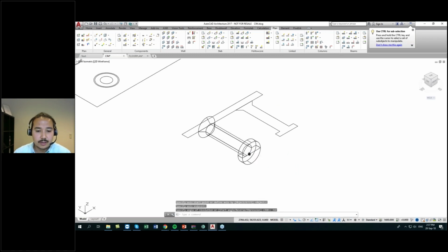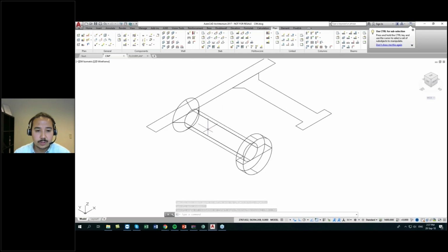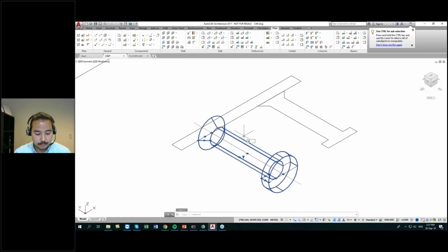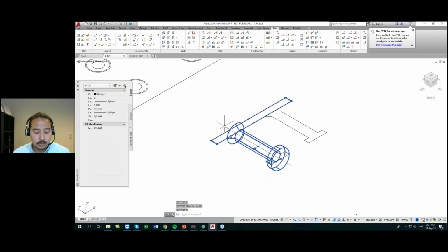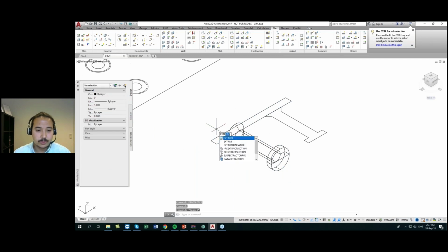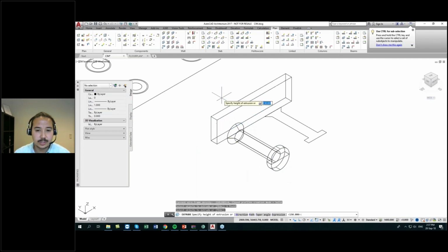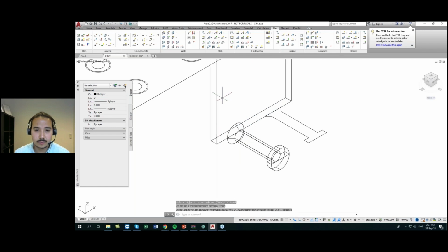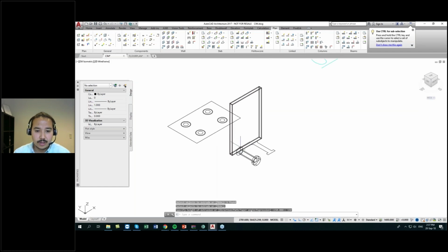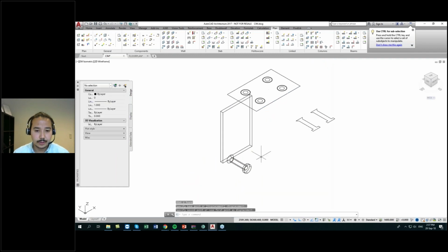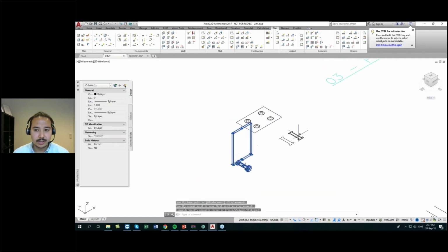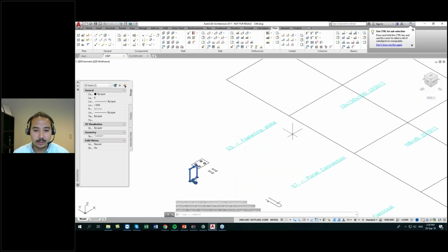So now the polyline I drew is this 3D solid. If we look here, 3D solid. I will also extrude this one here, because I want it to be a fastening plate, of course. So now I have these two things here, and I will just move here. I need to 3D rotate it, because when I put it in here on my grid and into the database, I'm going to look from the top.